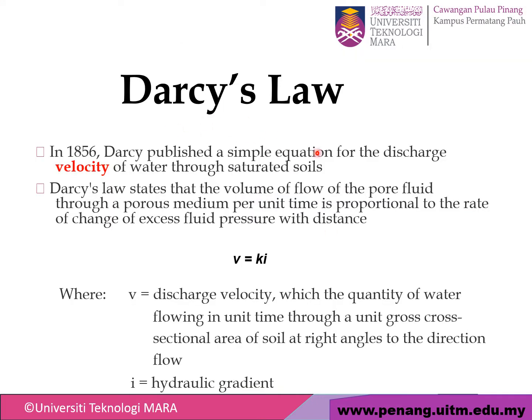Alright, this is Darcy law. Darcy law states that the volume of flow of the pore fluid through the porous medium per unit time is proportional to the rate of change of excess fluid pressure with distance. So v, which is discharge velocity, is equal to K i. K is the coefficient of permeability, i is the hydraulic gradient.